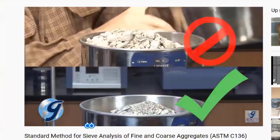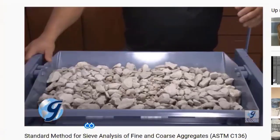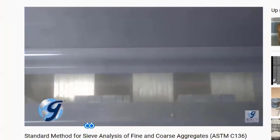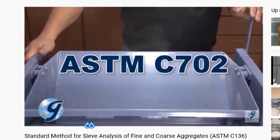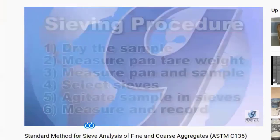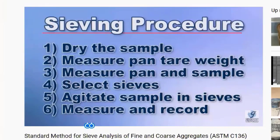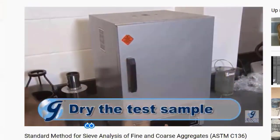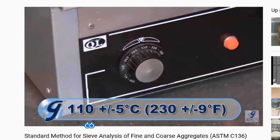For this demonstration, the bulk sample has already been reduced to an amount suitable for testing using the applicable procedure described in ASTM C702. The procedure for standard test method for sieve analysis of fine and coarse aggregates, we first dry the test sample in an oven at a constant temperature of 110 degrees Celsius.